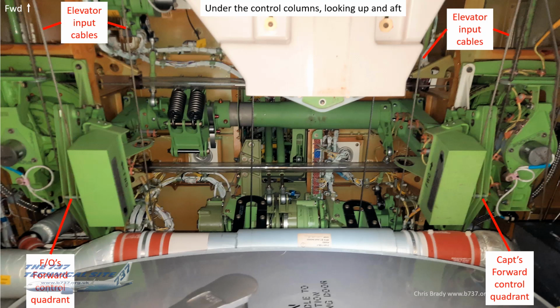But my point here is that there are a total of 4 cables. So it's not a single loop. It's actually 4 cables, and that is an extra level of redundancy. So if a cable should break or jam, or anything should happen, you've still got a cable to have some level of control.